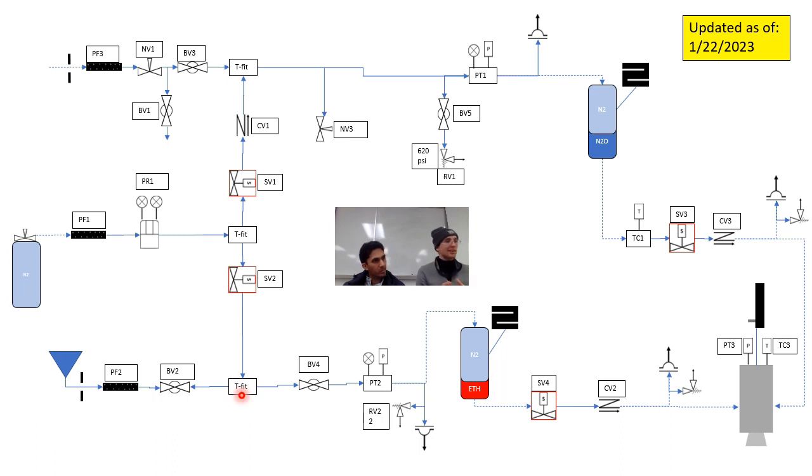So we've isolated the 2 cups of ethanol into a bottle. Then what we do next is lower the pressure regulator to just above 1 atmosphere. We want to make sure SV1 is closed, so we keep the nitrous oxide side as clean as possible.